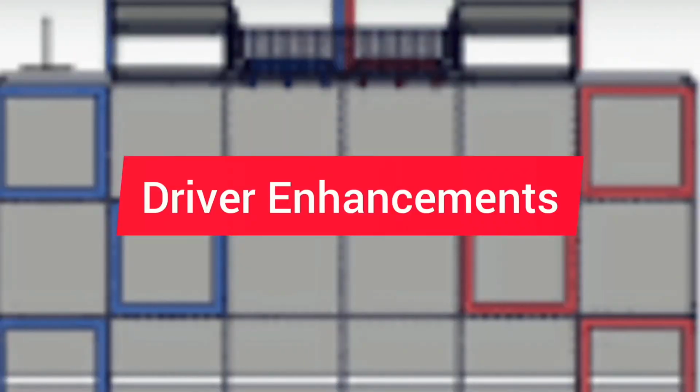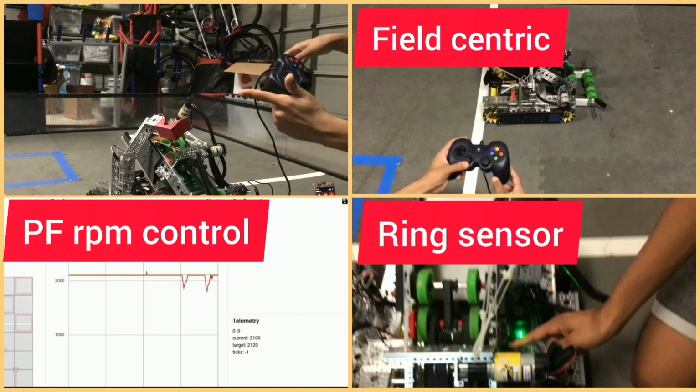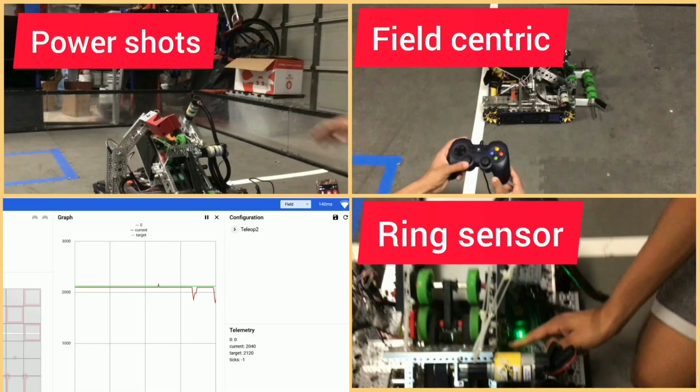We created a series of driver enhancements which use the sensors to ease the driver's experience. For power shots, we have a button for 3 specific angles so it automatically turns to shoot all 3 power shots. We use a built-in proportional and feedback controller which adjusts the shooter RPM based on the error, allowing for accurate shooting.